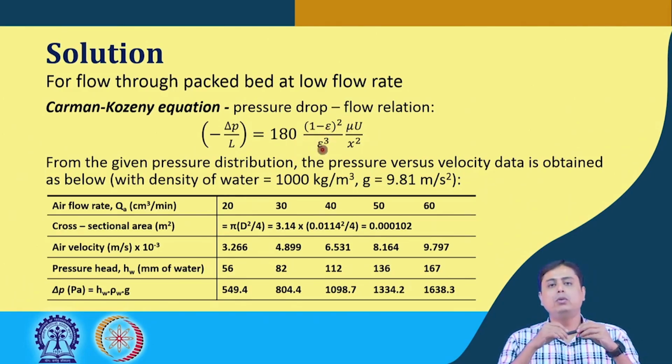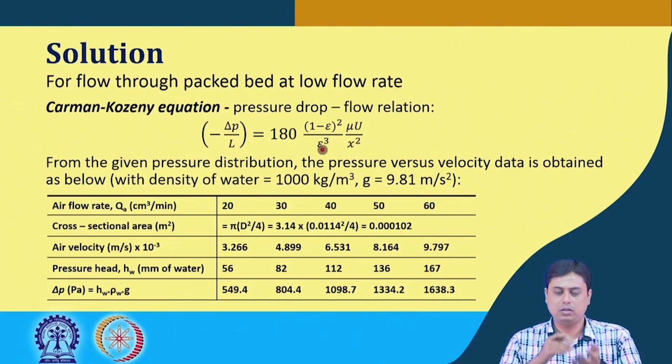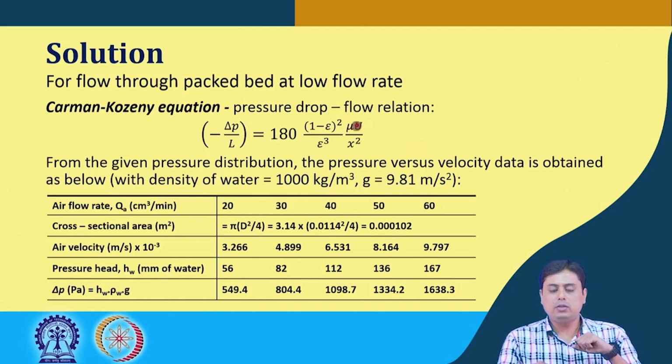That means, when you fill a cylindrical apparatus with a powdery sample, along with the particles there will be some void spaces between the particles, that is called the voidage. Voidage is the volume of empty space per unit volume of the apparatus, which is denoted by the epsilon value here.